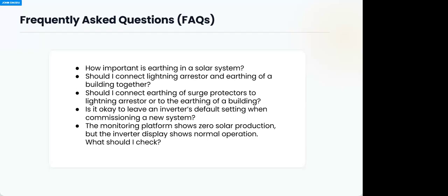So if it is earthed, when you touch it, you may not even know. But the fault is somewhere. And if it's heavy, because of other breakers, if heavy current wants to flow through that section, because the equipment is earthed, a breaker will trip, which is a signal that there's a problem. When you put it on back, it will trip again. So if it's an installation that is equipped with earth leakage and all those protective devices, it will trip. You know that there's a problem. Make sure you test, check, and resolve it before you continue to use such system. So it is very important to have everything connected to the system.